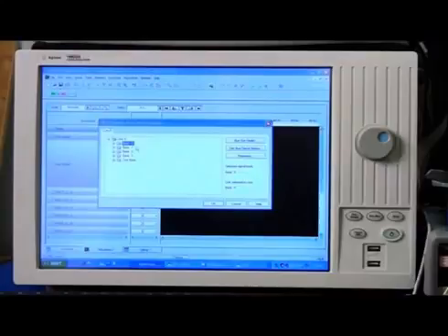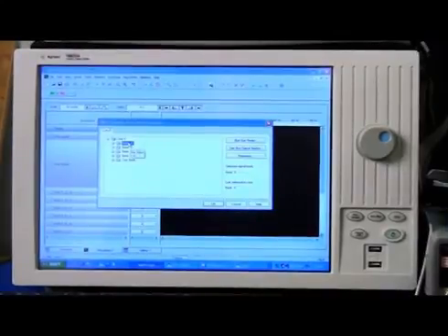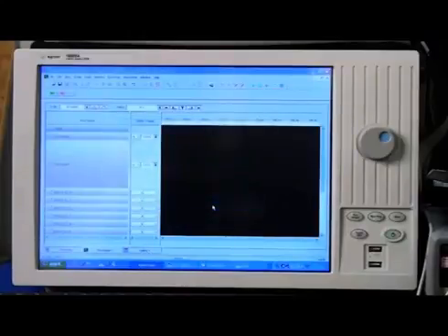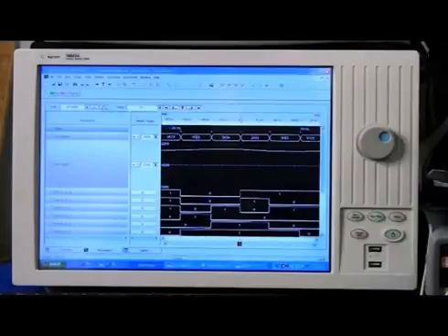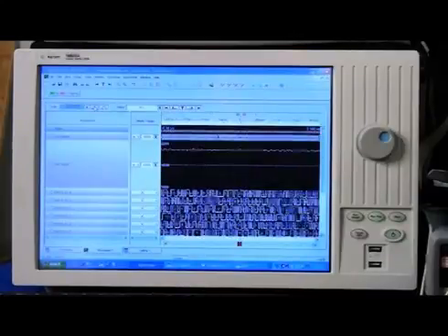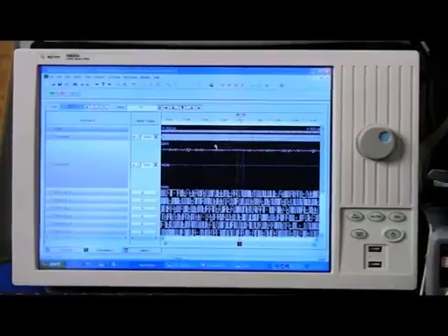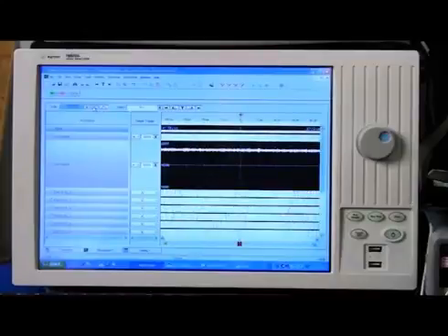Well, we've got a probe point inside the FPGA for that DAC input. So we're going to select that. Now we have that DAC input as our signal to view, and I'm going to press run. Here is that digital view in hex of the digital DAC input signal, and if we change our time per division, there is that view through the chart mode. So it looks right. That's the kind of thing I was expecting to see for an LTE signal.